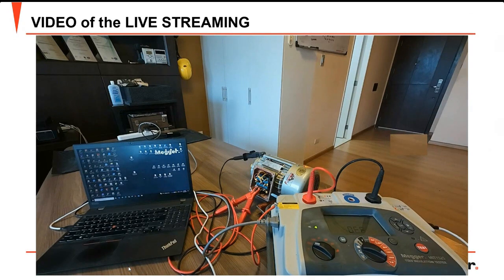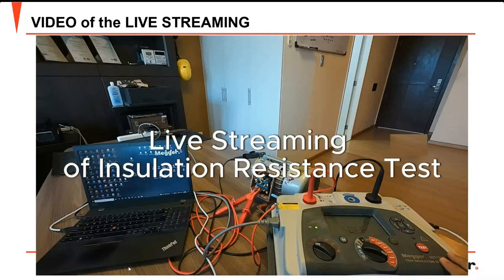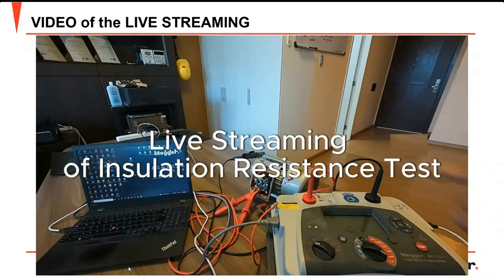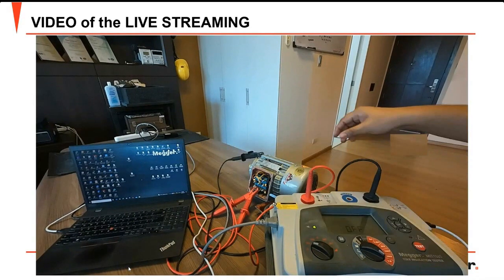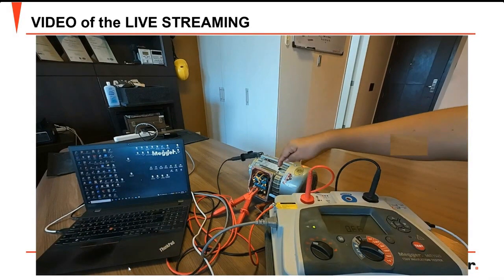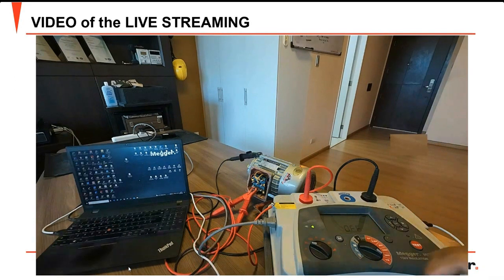So guys, I'm going to teach you how to do a live streaming while we do the insulation resistance test using the MIT 1525 here, and we will try to test this small motor here. We are connected at the moment to the coil and to the ground. So my PC is connected via this white cable, or USB cable, here.